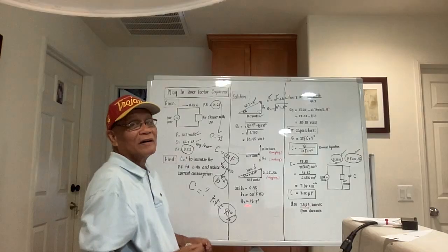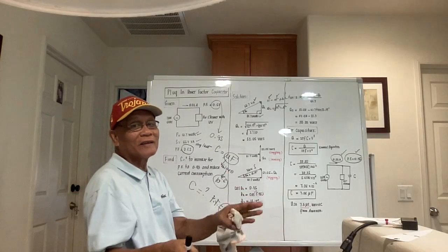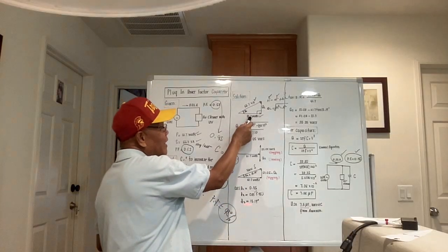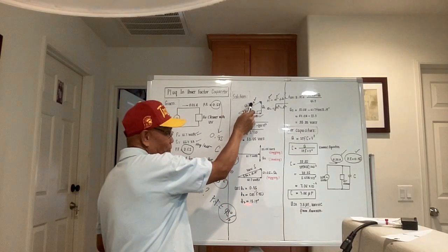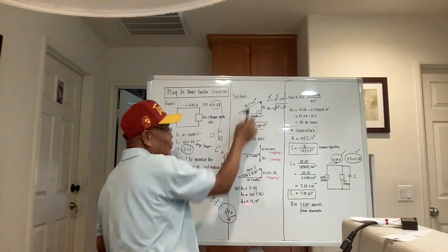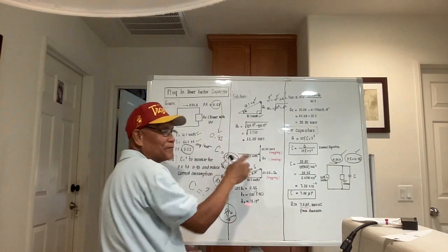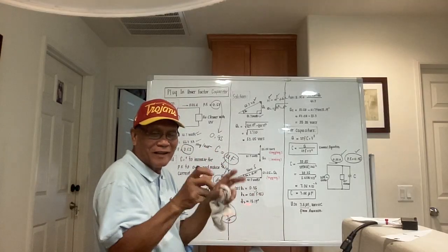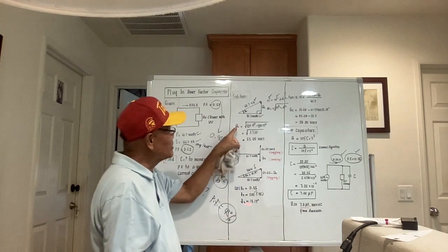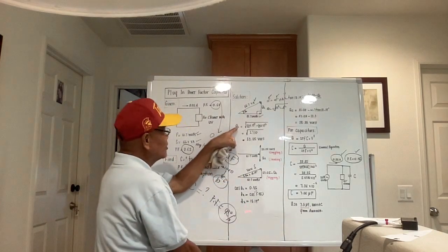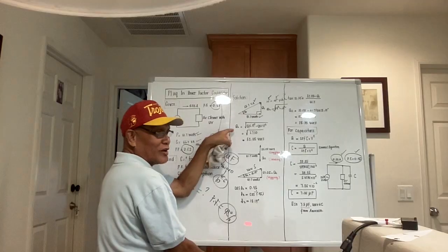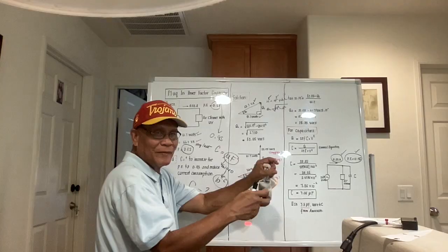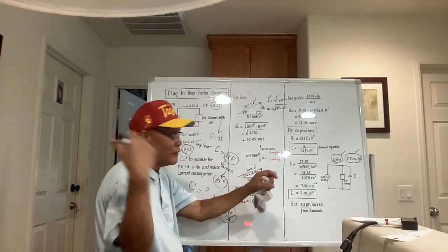Okay? A combination of AC circuit and what we call trigonometry. So if we know the adjacent side and we know the hypotenuse, we could compute for this, which is actually Q sub L, the reactive power which consumes so much energy. That's why our electric bill is actually very big. We must lessen this one. We could make this 0 or a certain value which is very negligible, so that it does not contribute to a big current passing through our meter.